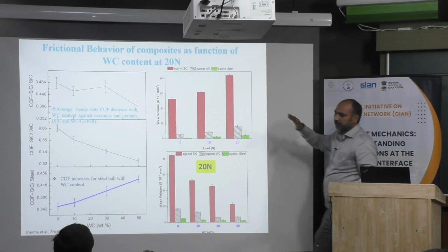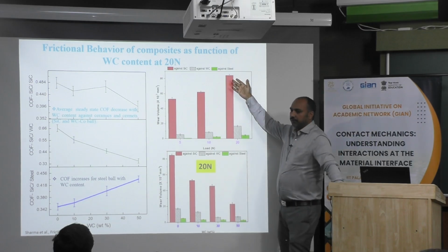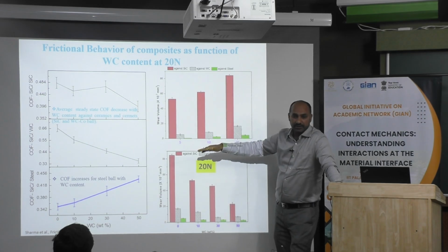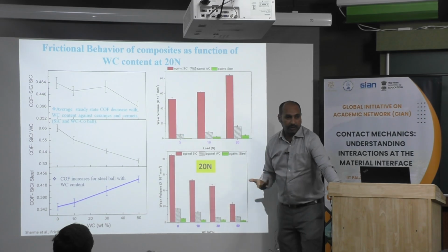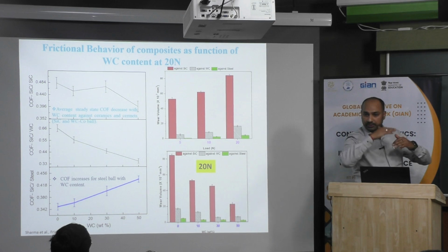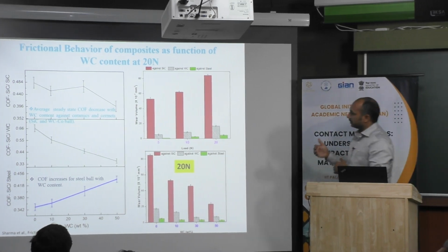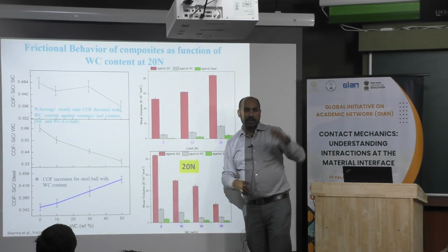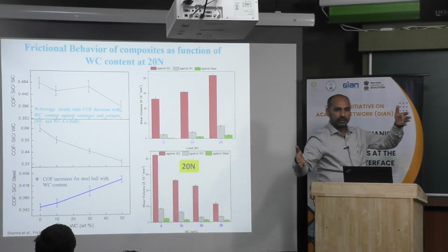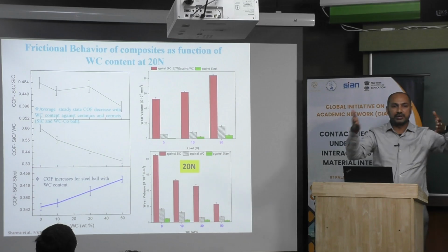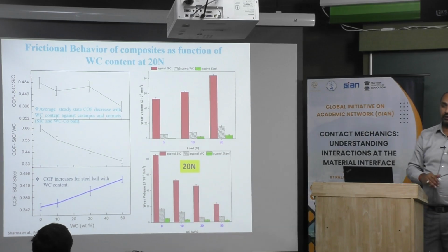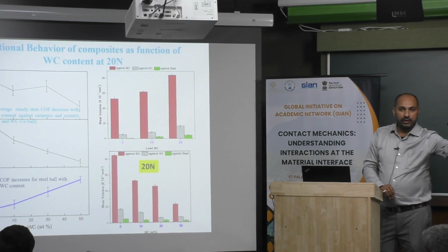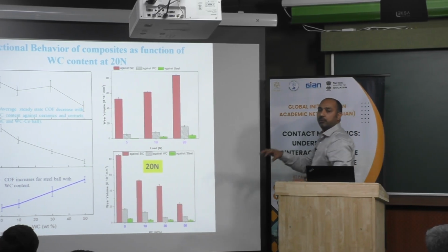That is being considered, and we get very high wear against the hard phase, where wear is less, but for the cermet phase it is drastically changing. You can say this is one order of change if you go from ceramic body to cermet body. That can be considered on the basis of their hardness, because our ceramic composite itself has hardness around 24 GPa, and the counter body has 14 GPa.